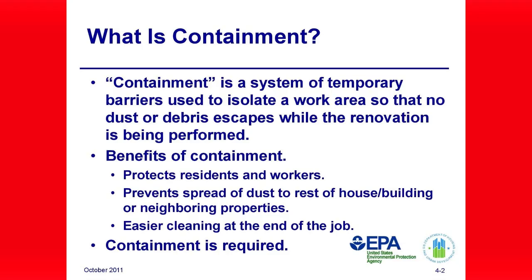Containment is required by the RRP rule because it reduces the risk to you and residents. Following the work area setup requirements for this module will protect you and your coworkers and residents by confining lead-contaminated dust and debris to a defined and demarcated area. Confining the lead is an important consideration in avoiding exposure. Reducing the risk to you and coworkers is also dependent upon the use of personal protective equipment.